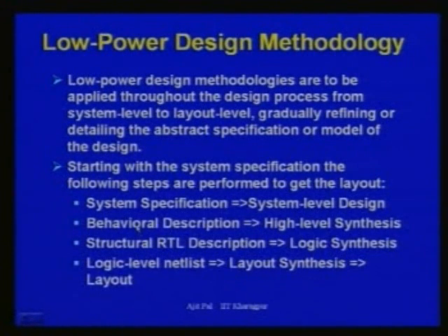Then you will start with a behavioral description. From that, you will perform high level synthesis or RTL level synthesis. From the structural RTL level description, you will go for logic synthesis, and from the logic level netlist, you will go for layout synthesis, finally to get a layout.